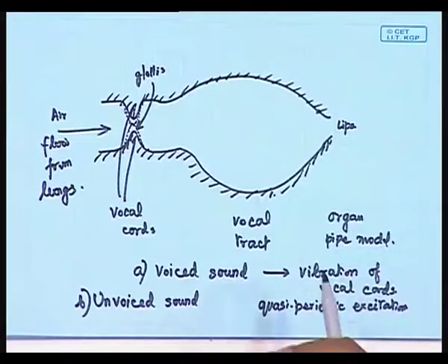So, that is what I was also telling you, that the entire speech processing model is so dynamic, okay, it changes with time, and it is only a quasi stationary behavior that helps us in producing a model. Because there is a quasi stationary behavior, that is why we can have short time speech analysis and at least try to extract the speech parameters, okay.